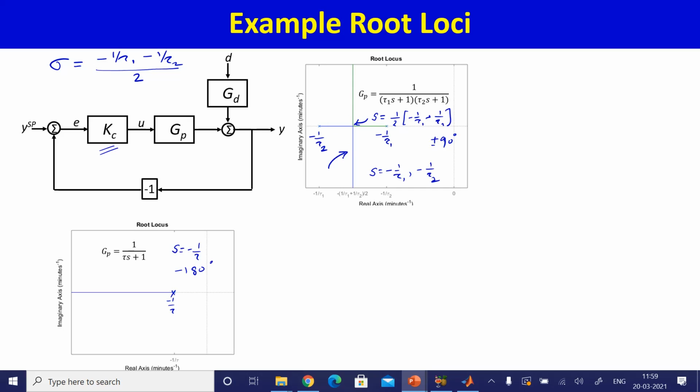And you can see that for a first order system or a second order system, the root locus never goes to the right half plane. A first order system doesn't even show oscillations because the root is always real and negative. A second order system can show oscillations because for sufficiently large Kc, you get complex conjugate roots. However, these complex conjugate roots never cross over into the right half plane, so first and second order systems under P control will always be stable and will never go unstable.